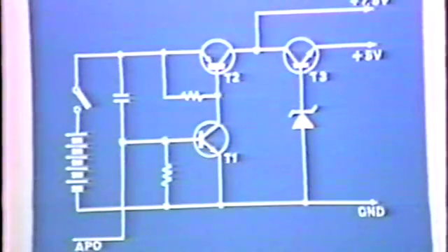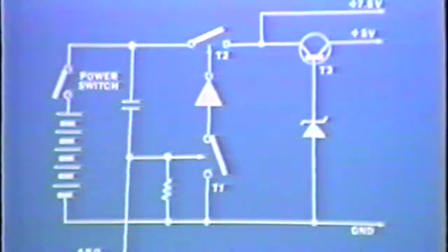To end part 2, we will explain the power circuit. This circuit is important because it supplies voltage to all of the other circuits, so it must be fully understood. This is the battery-driven Casio tone power circuit. Transistors perform switching operations and can be replaced by switches.